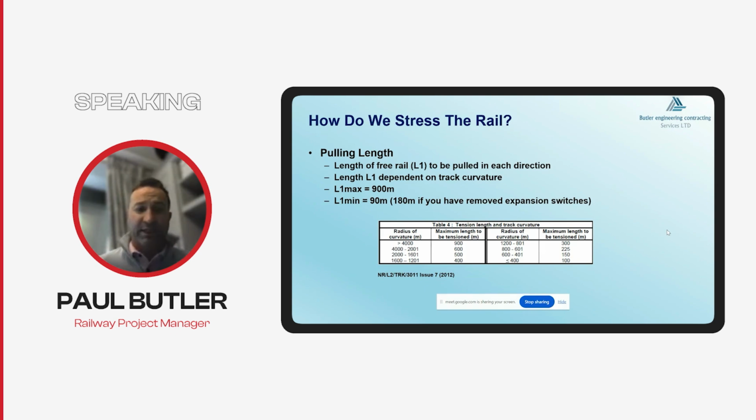The Network Rail standards are quite specific about how long these legs can be, dependent on the curvature. So you can see from table 4 here, as the radius of your curve decreases, the maximum length that you can stress on any particular leg also decreases.